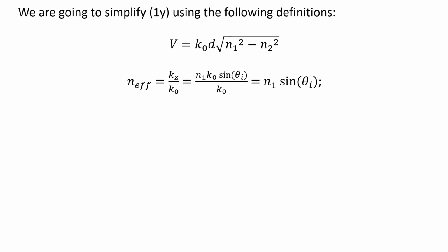It is defined as n1 divided by Kz divided by K0, and it is actually the parameter measuring the refractive index in the presence of the incident angle. Yeah, with the incident angle here, the effective refractive index will be lower, and this is the key for this.